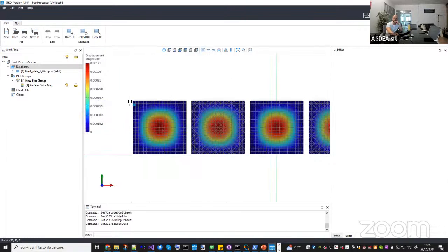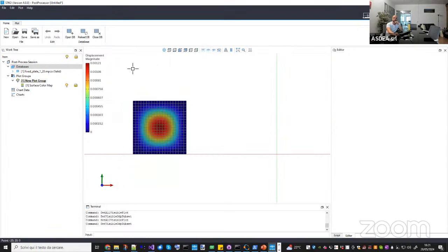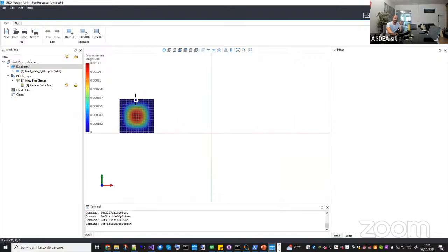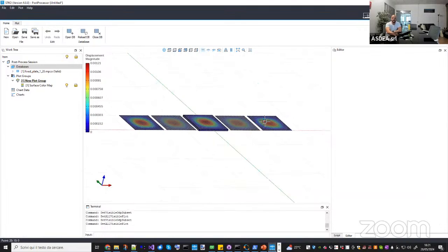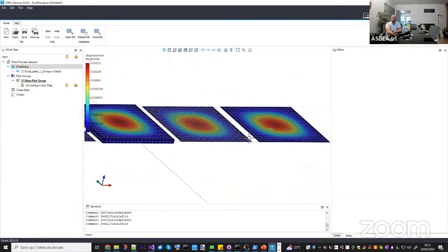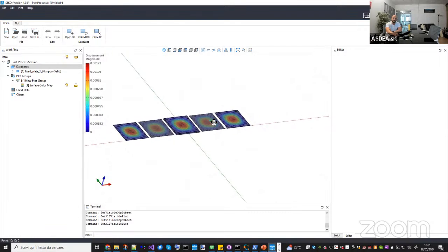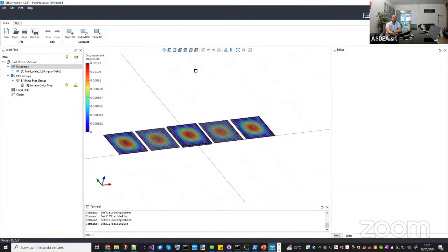And if we go to the thick shell element, either the quad or the triangular element, we are still at the same value, okay? So the thick shell element is able to capture the response even in the thin shell limit, and then I will talk about this, okay? As you can see, the thinner the shell, the better is the prediction of the thin element. But the thin element cannot be used in the thick limit, okay?